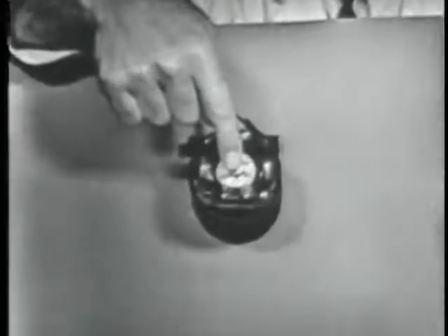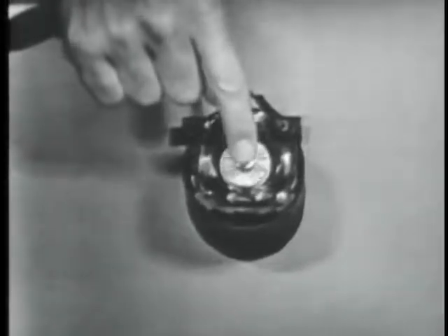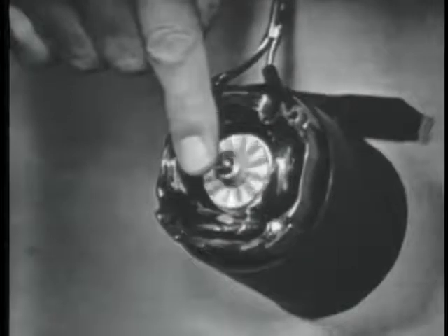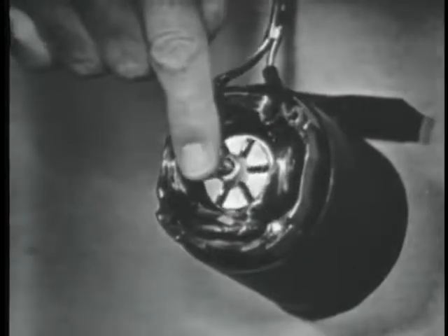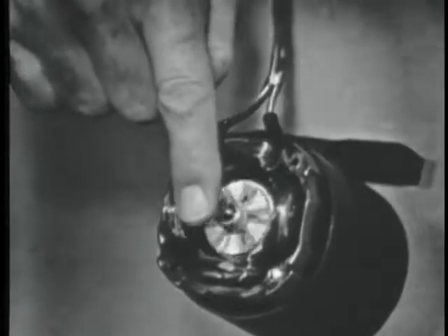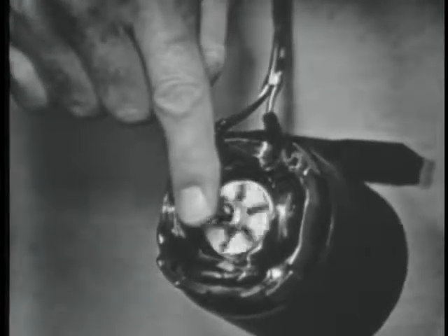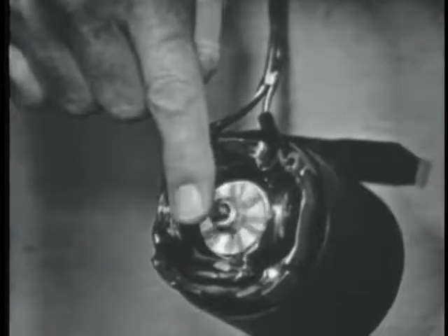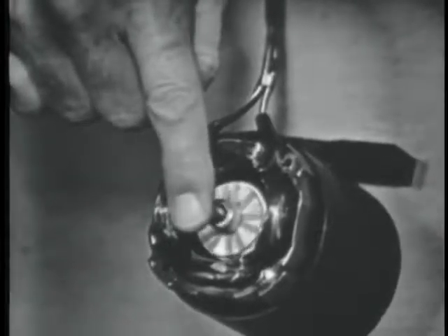The load of the fan causes the rotor to slow down, just as I can do with my finger here. I can cause the rotor to turn slower. Now, as it slows down, the slippage increases, and the frequency at which the conductors of the rotor are cut by the rotating flux lines increases. More current flows. The magnet becomes stronger and compensates for the increased load. Now, there's a limit to this.